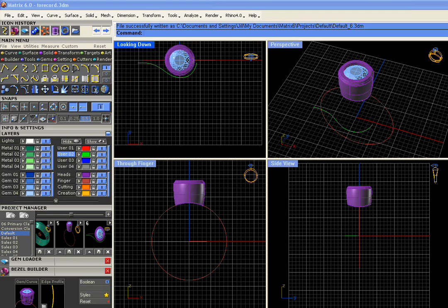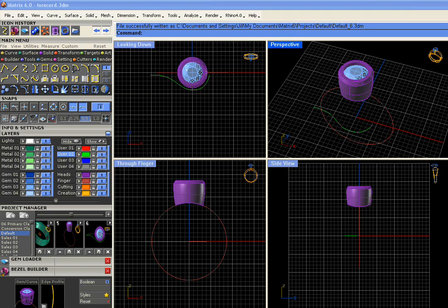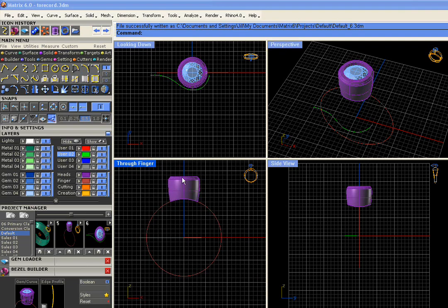In order to run curve from two views, it has to be flat. So one way to get it flat is simply turn on project before you begin drawing it. If yours isn't flat when you come back here to look at it, if you snapped up here somewhere, delete the curve, turn on project, and make sure you've got it turned on all the while that you're drawing. Okay.